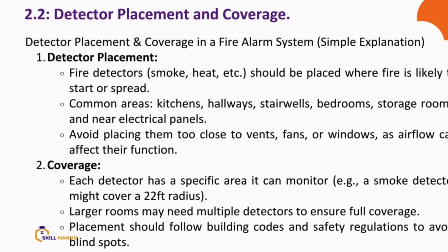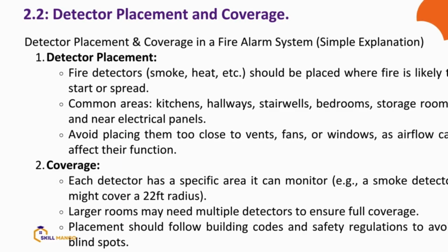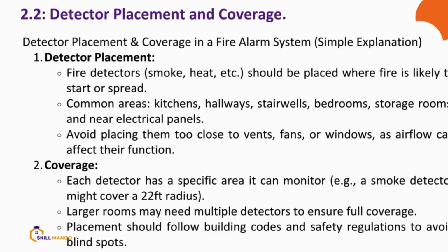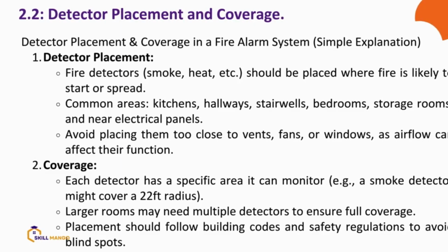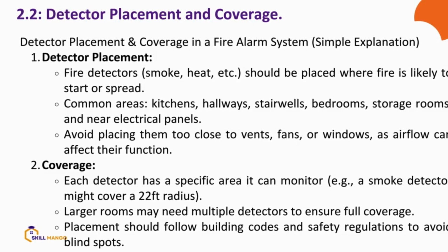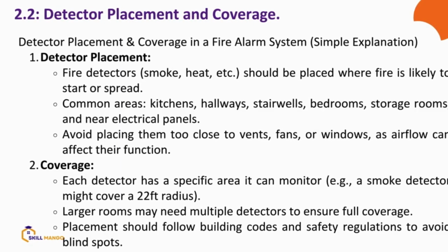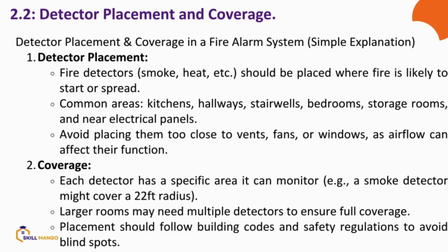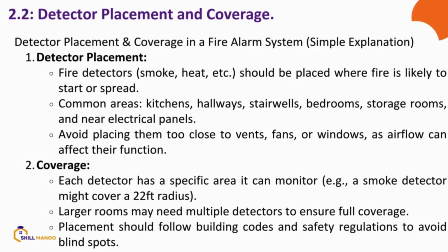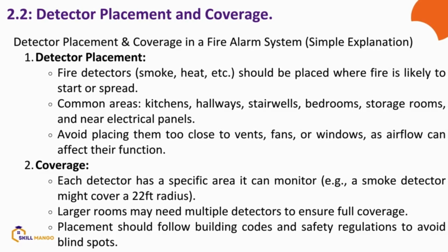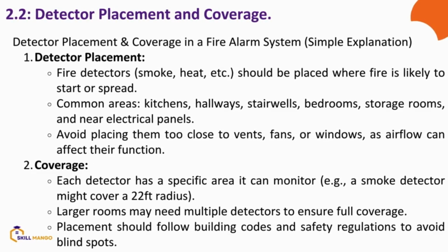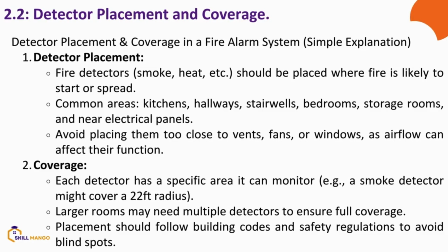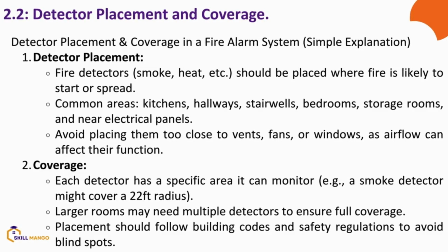So each detector also has an area that it can cover. You have to look at the specification of your detectors when you're buying them. Pay attention to these specifications. They are very, very important because that will determine the number of detectors you're going to buy, how to mount them, and the best angle to position them. When you're buying a detector, pay attention to the specification. It's very, very important. All right. So let's pay attention to all these things when we're buying detectors.